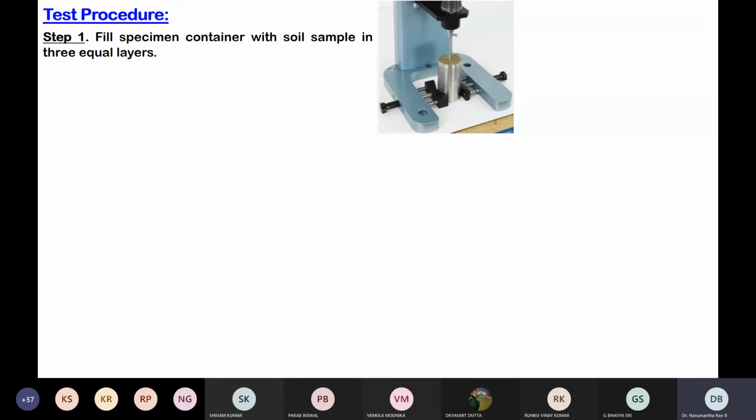The Vane shear test is not valid on fully compacted soil samples. So if it is a compacted soil sample, in the field or in the laboratory, it is suggested to avoid conducting Vane shear. We have to take the clay sample with large moisture content. That is the requirement. So take the clay, add sufficient water, make it something like a paste, and fill it in the container, so that the sample preparation is over. No compaction, nothing.